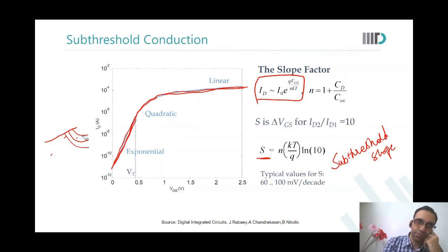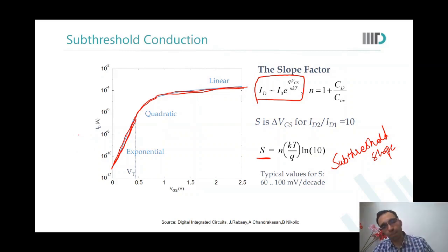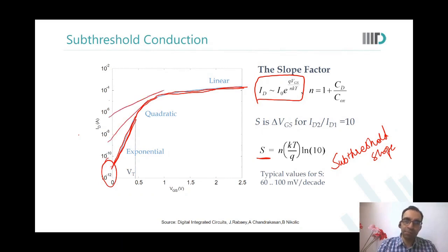So basically, in this graph, one thing, sir. We want low VT, no? Because more leakage will occur due to low VT, sir. According to this graph, more leakage. No, we want less leakage. So that's why VT should be higher. Your VT should be as high as possible ताकि leakage कम हो जाए. So that when your gate is at 0, you have as low current as possible. But in advanced technologies, you will see that this is what happens.